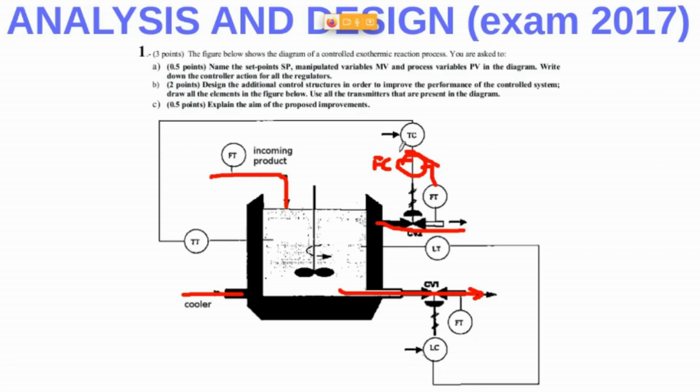So, an inner or auxiliary control strategy is added in here. My proposal is to build a cascade control loop here. Remember that it doesn't imply buying a new device. The same temperature controller can do the flow controller action, right? So the device will be configured in a cascade way.